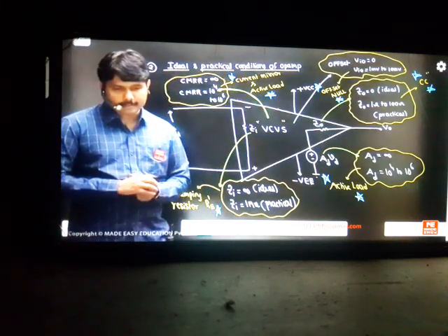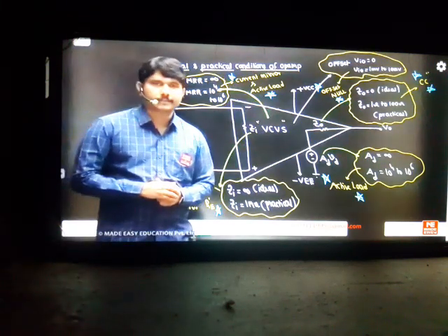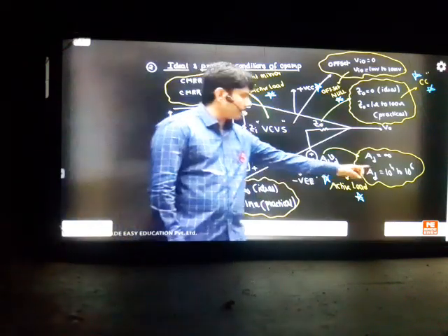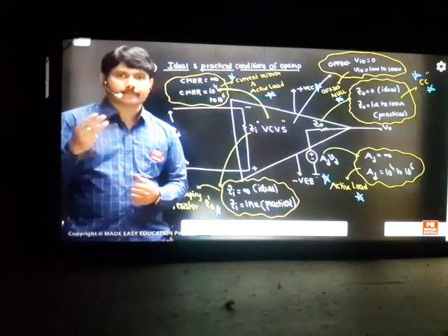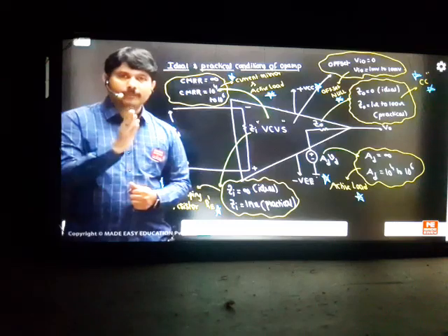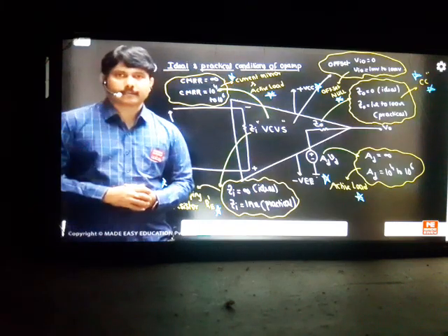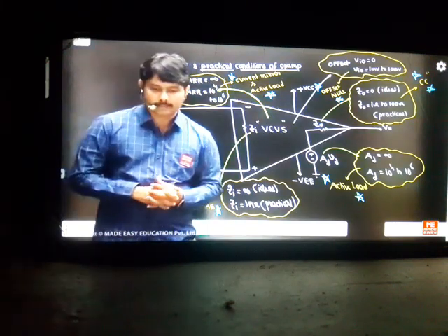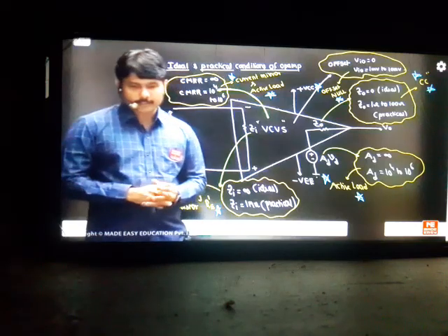And Parthasarathi, you're asking what is inside the op amp? Two differential amplifiers. Yes, inside the op amp we have two differential amplifiers which can give a gain of 10 power 4. If you take three differential amplifiers, we get a gain of 10 power 6. So the limit is 3 max. Some op amps can be designed with two differential amplifiers, some can go up to three. Don't go more than that because the IC size will increase.